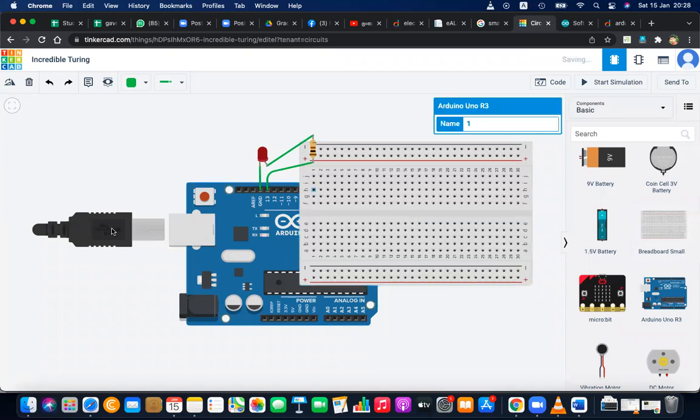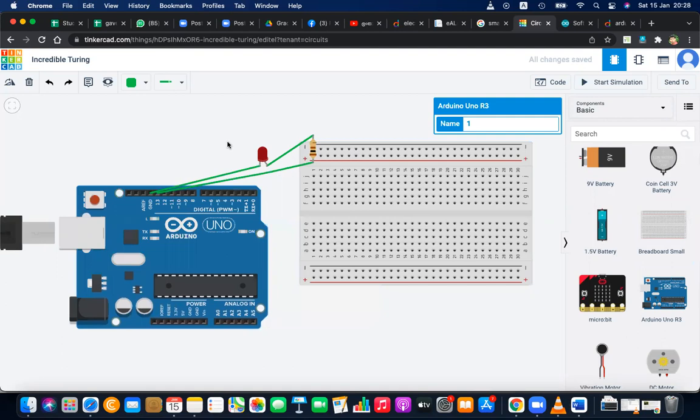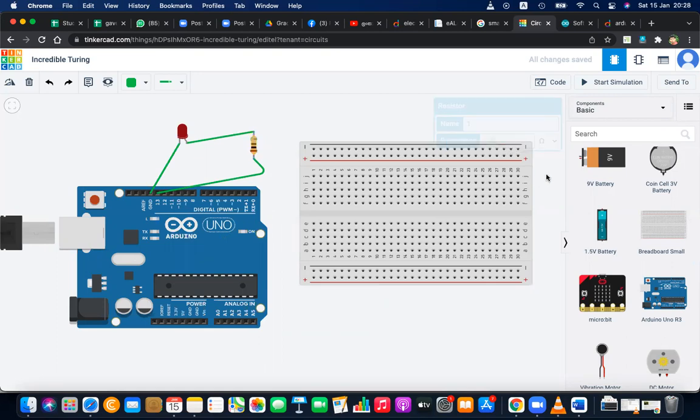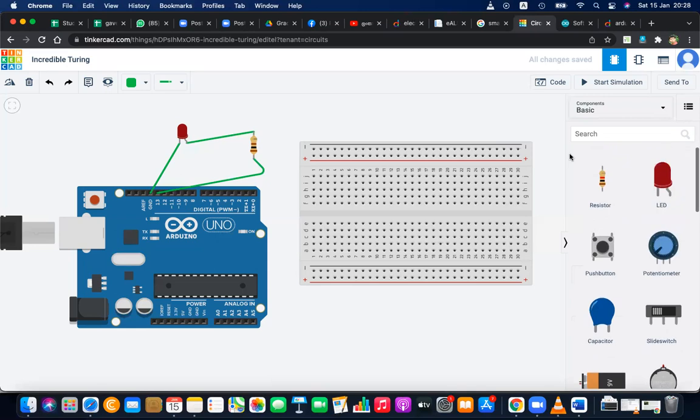A breadboard is a special piece of equipment where the connectivity can be expanded. Here, all these are connected, and all these are also connected. These are connected vertically, and these are connected horizontally. Therefore, I can connect some bulbs. Okay, let's connect some bulbs.